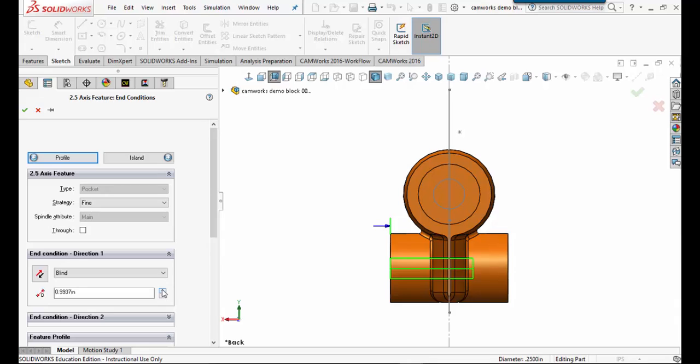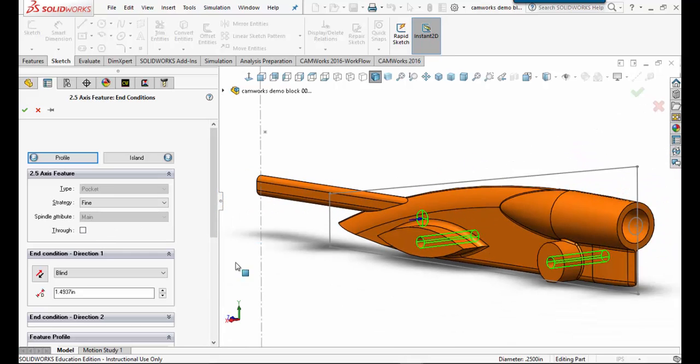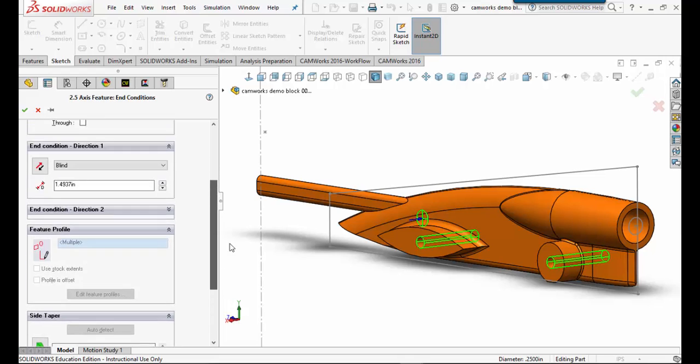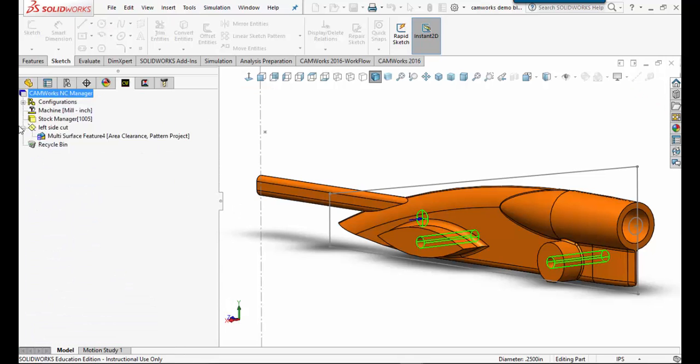This is one we got to be pretty careful on when we did our mill part setup. That looks good. Okay, again, if we were just using a 1/8 inch axle and we weren't worried about putting a bushing in, we'd have said the drill would have been fine, but that's not going to work. So I like this, and let's check any other parameters here we might be missing. I think we're okay on that, so we'll go ahead and check that off.